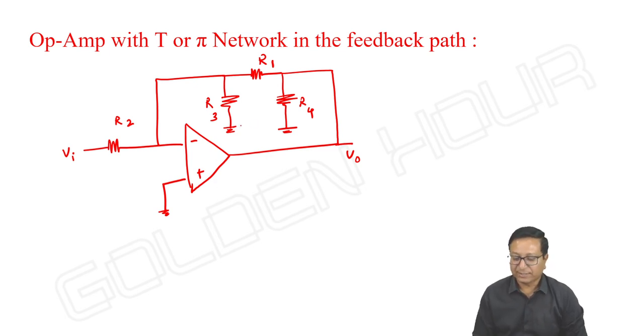Then the same circuit, if you observe, due to virtual short, here the voltage will be 0. And this is output. We are well aware of this point. Here, just look at this resistor R3. This point and this point are one and the same. Instead of showing R3 from here to ground, I can show R3 from here to ground. Possible.